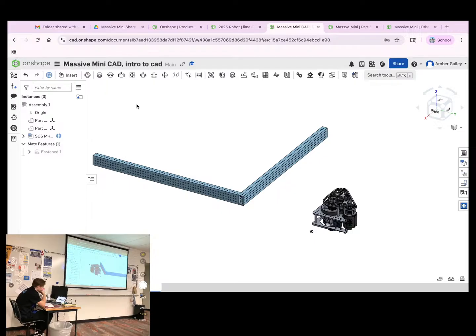I won't lie to you guys. Using MK CAD is pretty bad, especially for a MacBook. Using these parts that are really dense, that have many components, makes it really hard on your computer, and it makes your performance tank. There have been times that I have been unable to do CAD because of that. I just quit. I'm like, you guys can do it. So be very careful with inserting very complex parts in MK CAD.